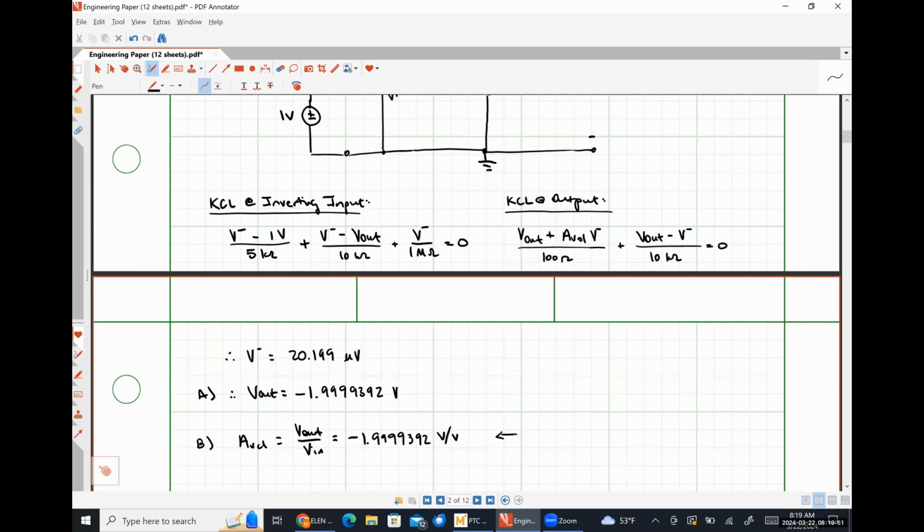On that data sheet I showed you guys, the typical or average value was 200 volts per millivolt, but the minimum value they have observed is 75 volts per millivolt, which is appreciably different. So the open loop voltage gain isn't a quantity that we can inherently rely on. Negative feedback used in this way provides us with a reliable, repeatable, finite voltage gain. That's one of the reasons it's used.